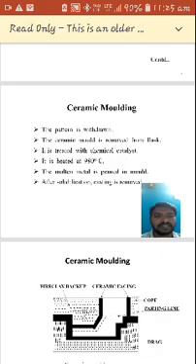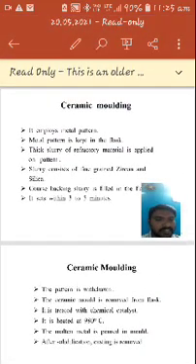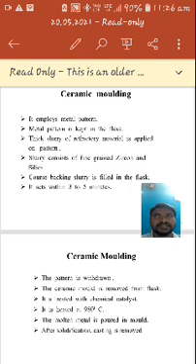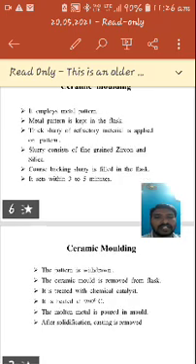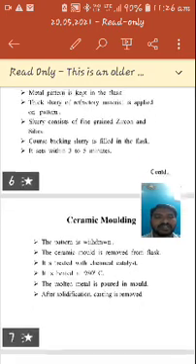The molten metal is poured in the mold. After solidification, the casting is removed. So this is about the ceramic process. It is used for metal patterns. Here we additionally use a slurry of fine grained zircon and silica. Within 3 to 5 minutes, the mold will be set.